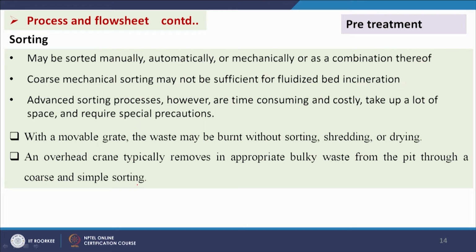So, sorting: the MSW may be sorted manually, automatically or mechanically, or as a combination thereof. Coarse mechanical sorting may not be sufficient for fluidized bed incineration. Advanced sorting processes, however, are time consuming and costly, take up a lot of space and require special precautions.